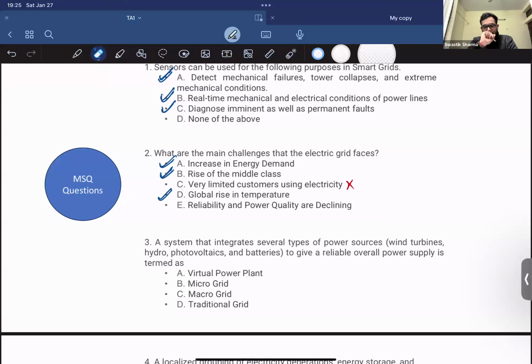It's renewables, right? So you have solar PVs, they are being integrated through inverters. Inverters are power electronic loads which are non-linear in nature. Due to the rise in PVs, these renewable resources in solar rooftop as well, or at different places at transmission side also, there are utility scale wind farms and PV farms. These can deteriorate power quality, thereby decreasing the reliability of our electric grid. So this is also a major threat.